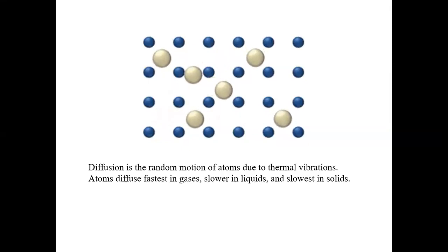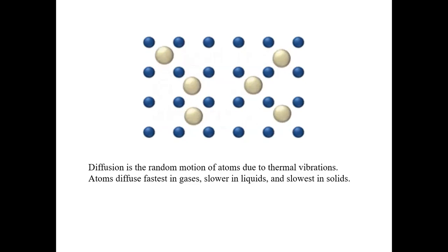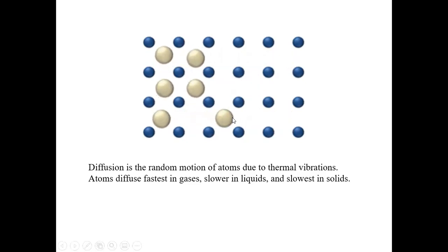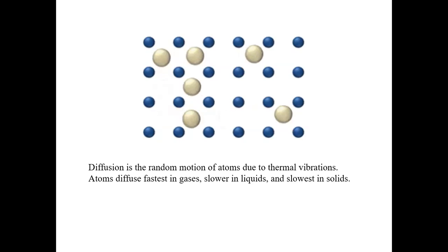This also illustrates that the key mechanism for interstitial diffusion is random hopping, because there's no particular direction that this particle wants to go. It can go in any direction. I'll ask you a question later about why, in this particular case, effectively all of the particles are moving from left to right. But if you look at a single particle, suppose there are no other neighbors around, there's equal probability for it to hop into any of the possible nearby paths. So that is a very intuitive understanding of solid state diffusion, in particular interstitial diffusion.